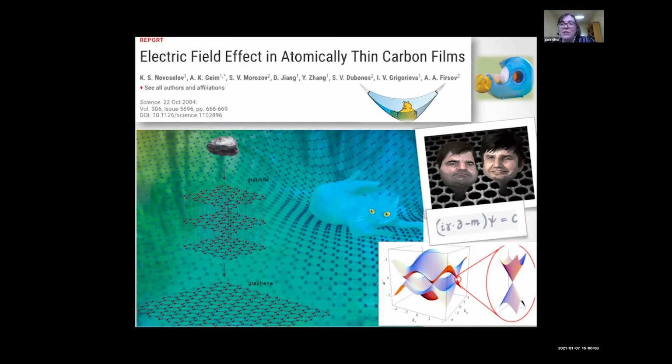That is different from a conventional semiconductor, where the bands which describe the dynamics of the charge carriers are mostly parabolic. These give effective masses to the charge carriers, making them heavier and affecting their velocities. In graphene, you have linear properties, making them like massless charge carriers.